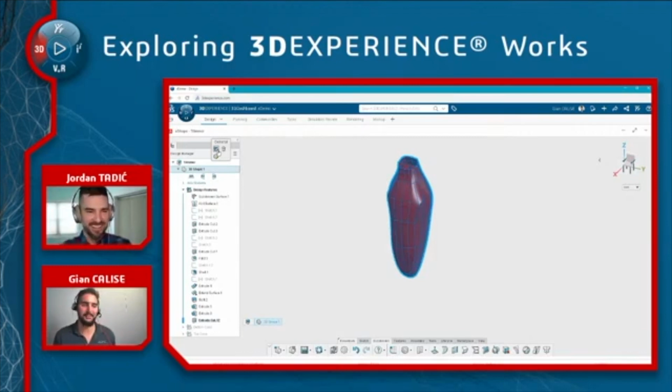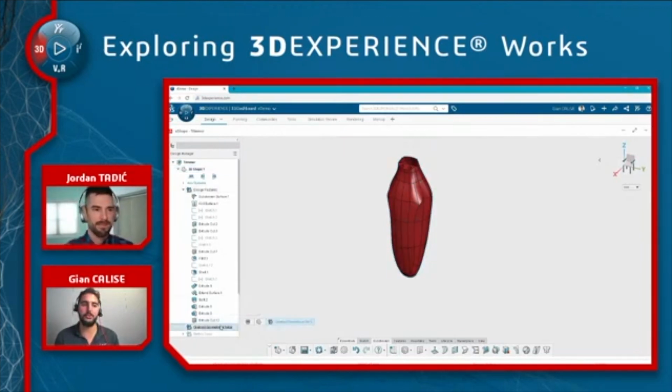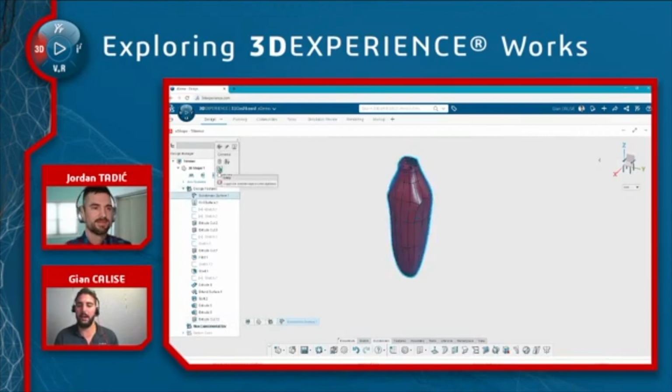But just to keep things clean, so we don't break what's existing here, I'm gonna make a new ordered geometric set like you did, but for a slightly different reason. I want to copy and paste that same sub D body into this new ordered geometric set, just to play around with it and see what kind of changes I'm feeling at the time. That's a great idea. That way you can preserve the original while trying out a new idea.